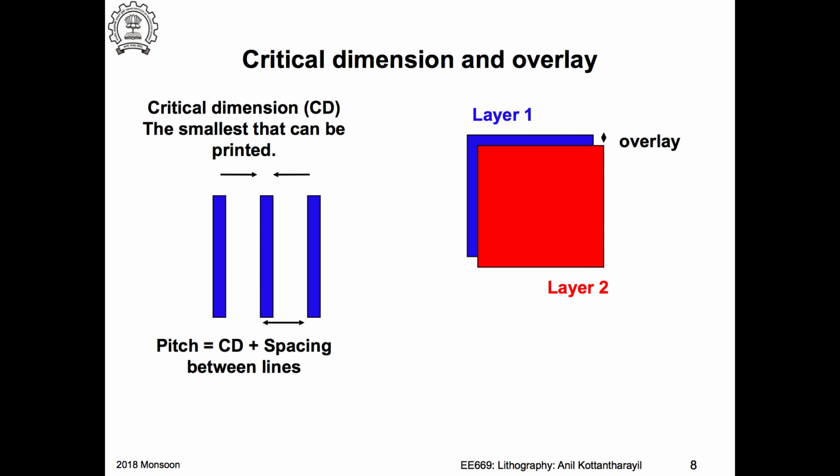And from the lithography system itself, the particles fall on the photoresist. Now, the optical properties of this particle and its dimensions would influence how much light the photoresist actually receives. So the defect that is generated would have an influence on the final features that I get on my wafer. Okay. So, a very important consideration for lithography. We'll briefly discuss it in the next slides.